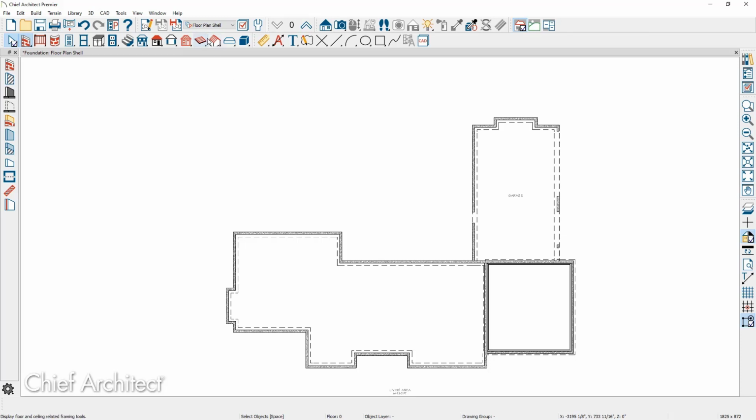Next to the drop down for the Saved Plan view is a Save Active View As. I'm going to begin there. I'm going to click Save Active View As, and I'm going to give it the word Foundation. And since I already have an existing foundation Saved Plan view, I'm just going to call it -1 for the purpose of the session. Once I've saved the foundation view, let's go into the Edit Active View properties.